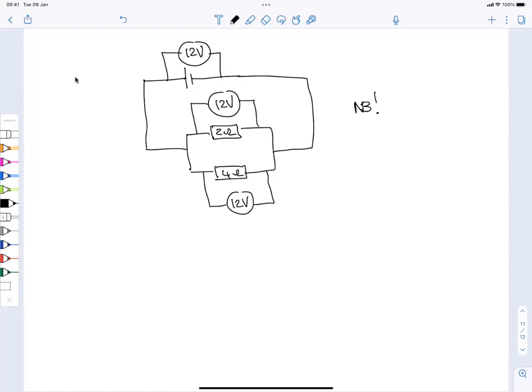Okay. Now, if we add another resistor in the circuit, let's assume that it's here somewhere. I'll color that one in. And we add 4 volts there. That means of the 12 volts, we've lost 4. So the potential difference to lose over the parallel circuit is only 8 volts then. That is very important. That's what's going to make and break this chapter for you.